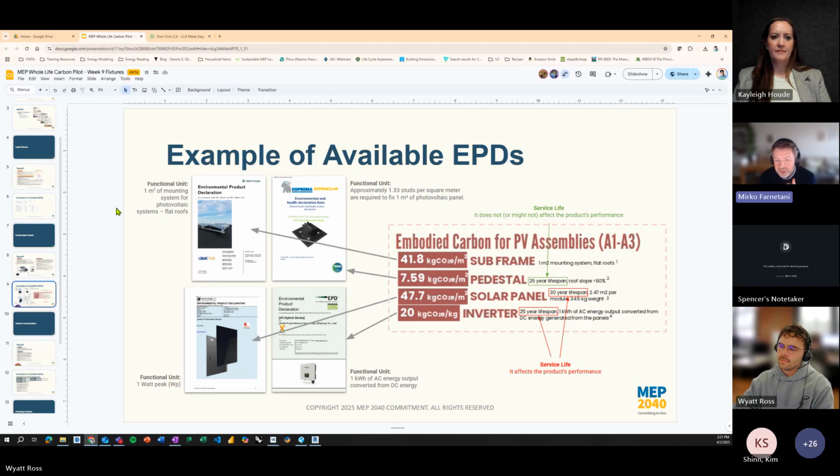So in this case, the results are mainly in meters squared and kilograms, whereas the EPDs' functional units come with different references as well. Of course, if you use One Click LCA, it is possible to convert units. If you don't use One Click LCA, and you do something manual, all of these calculations should be carried out by the assessor.